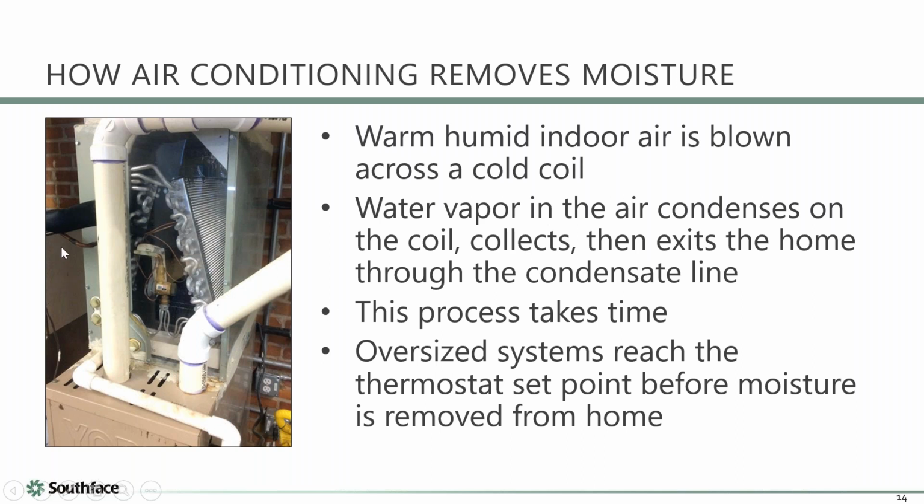In the summertime mode, in cooling mode, we're going to have the liquid come in. It's going to flash across a small orifice, which is a metering device. That's this expansion valve here, and it'll try to regulate the amount of liquid refrigerant that's in the coil. And it's always liquid at the bottom of the coil, and it's always vapor as it leaves the top of the coil. And that's why you have this cold suction line that's insulated up here.